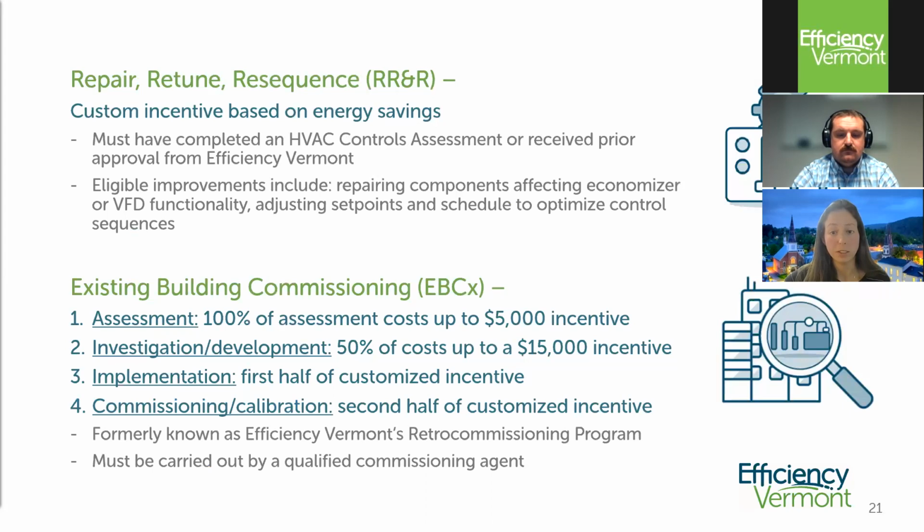Some customers may find it makes sense to complete repairs or retune or resequence their controls. That could be repairing components that affect economizer or VFD functionality, or adjusting set points and occupancy schedules, or adding in advanced demand-based control sequences like Nick was talking about earlier. Our R&R projects are eligible for custom incentives that are based on anticipated energy savings.